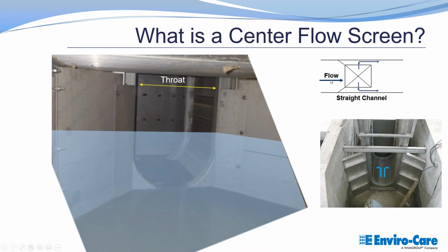One of the considerations as well is this flow comes in here, makes the turn, you can get a lot of grit deposition down at the bottom. So usually what you'll have is an opening in the backside that allows you to periodically open it and flush the flow through and keep the grit moving. It's an important part of the maintenance on this, because otherwise, as this belt comes around, it'll keep driving through the grit collected down at the bottom.